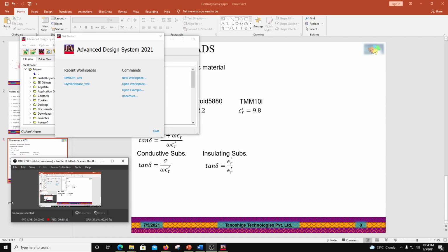So I'll show you various transmission lines on the boards and how do you design a transition from a planar line like microstrip to a coaxial SMA connector, for example. So that transition has to be designed, okay, or it can be a planar line like a microstrip to a waveguide transition. So I'm going to cover that in EM Pro, not in momentum.